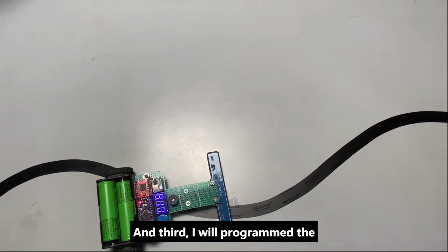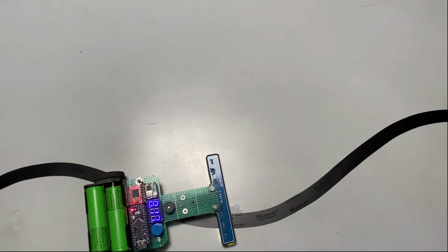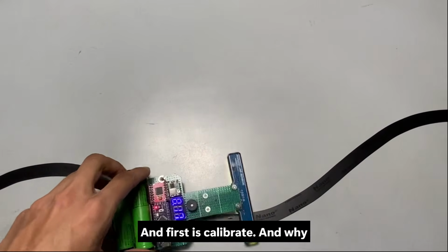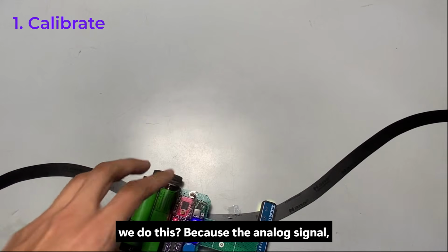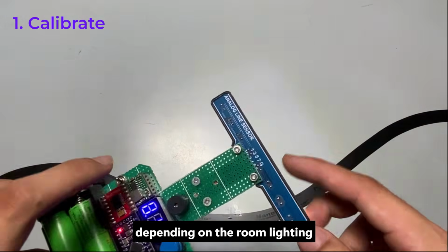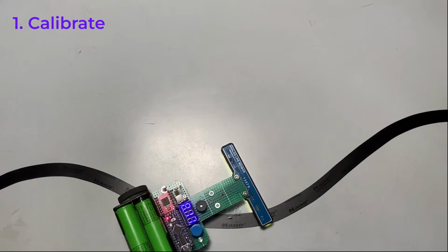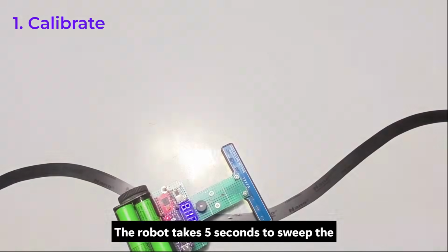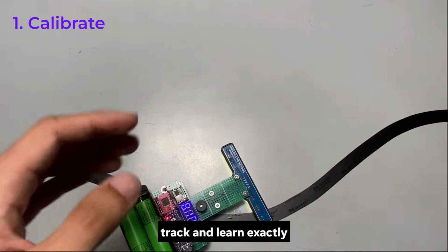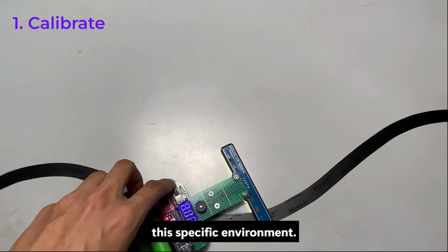And now, I program the robot with 3 distinct modes to make it completely autonomous. First is calibrate. And why do we do this? Because the analog signal from the sensor changes depending on the room lighting and the track material. The robot takes 5 seconds to sweep the track and learn exactly what black and white look like in this specific environment.